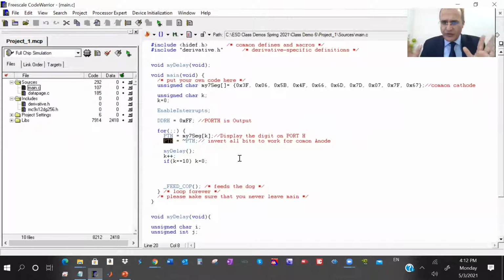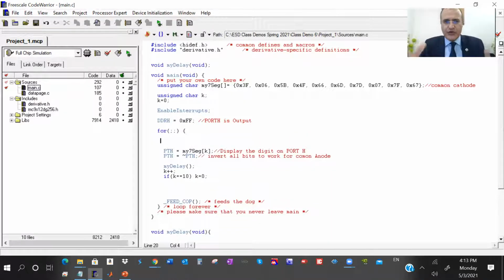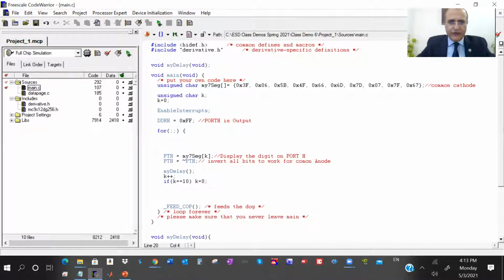I want to do it the normal way without an interrupt, then do it with an interrupt. So if I'm counting at any point of time, I want to push a button. If a button is pushed, I want to blink 10 times, right? So first, I need to define that DDRM equals 0x00, right? Port M, I'm going to make it as input. Port M is input.